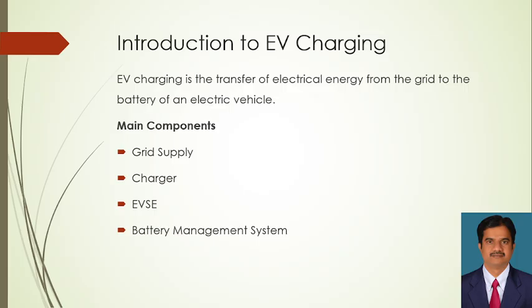We found SOC and SOH for practical real-time problems, and also the graph regarding battery charging and discharging cycles, and some techniques related to how to find SOC and SOH. Among these, the Kalman filter, or the modified Kalman filter, is the better known estimation technique for electric vehicle applications.